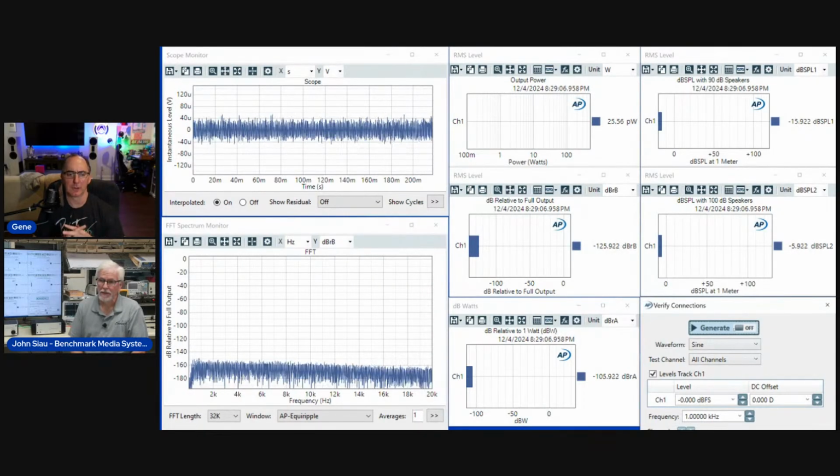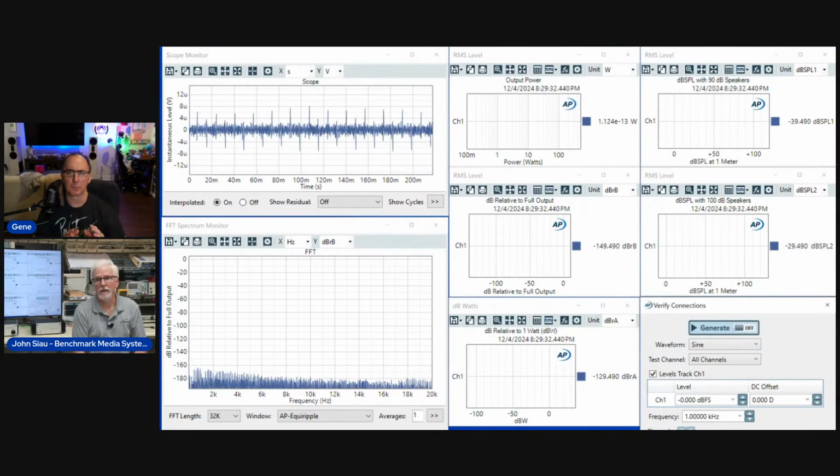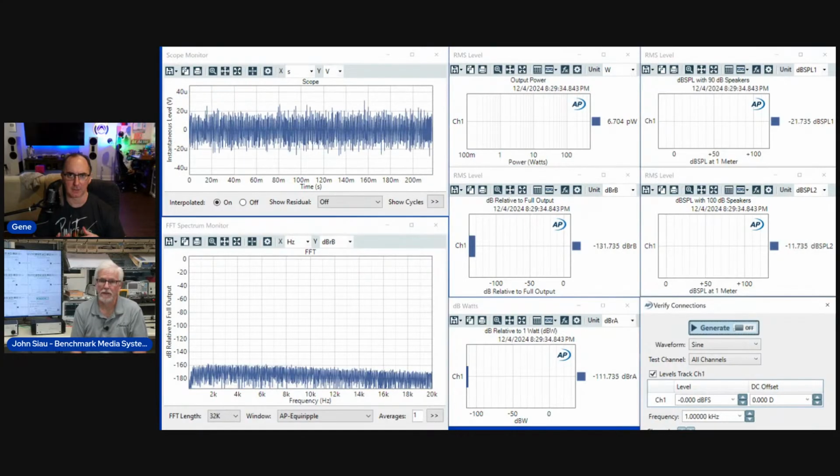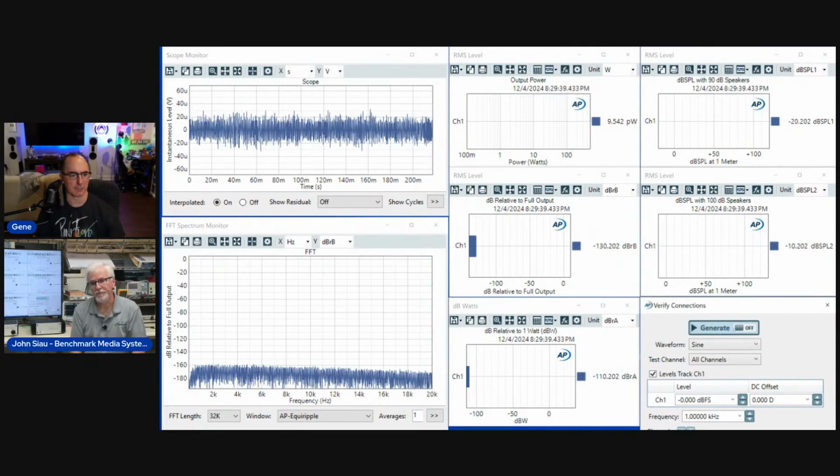So just to recap, the best settings in this scenario: you want your DAC on a fixed output, not a variable. That'll give you the 12.2 volt RMS output out of the DAC. Then you set the amplifier, the HB2, to the minimum gain setting, the low voltage gain, which I think you said was 9 dB. It's 9.2 dB of voltage gain, not to be confused with the current gain of the stage. And then you use the master volume of the preamp.